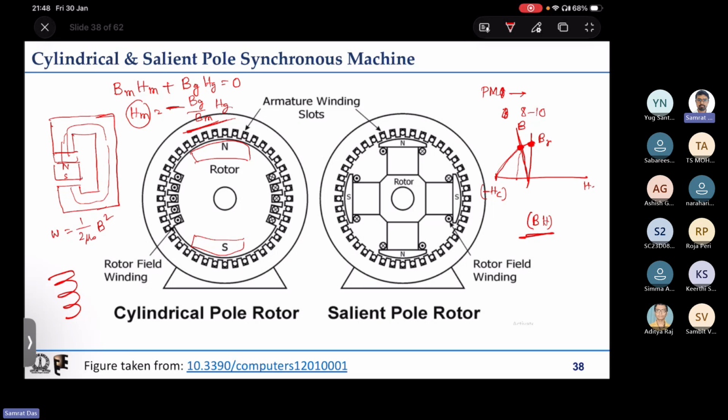All those practical aspects will come up, and that is why, even for the size of the coil, because you have to house the coil, and the cooling arrangement has to be done, and other things. That is why, for getting the same energy, for a permanent magnet this number is at least 8 to 10 times what we can get as energy density for a coil. But the size is not actually 8 to 10 times lower, because there are practical limitations in the flux density values.